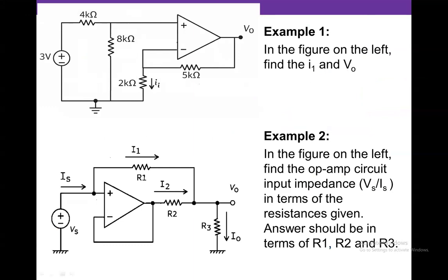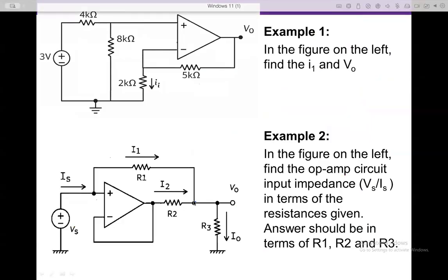So if you consider a node like this, a place like this, V1, if this is V2 and V3, what can you say about V1, V2, V3? Yep. It's the same voltage, it's the same point. If there's no component in between, if it's just connected by a wire, all of this has the same voltage. So everything that I'm drawing here right now has the same voltage.